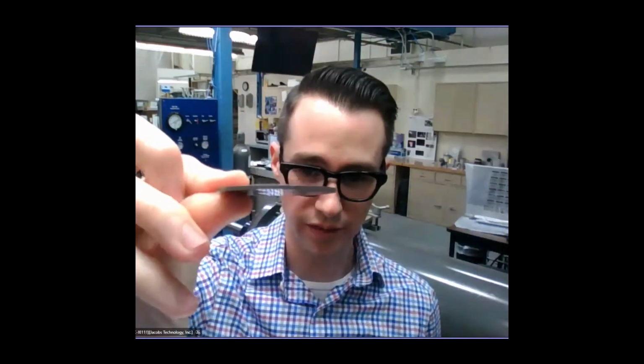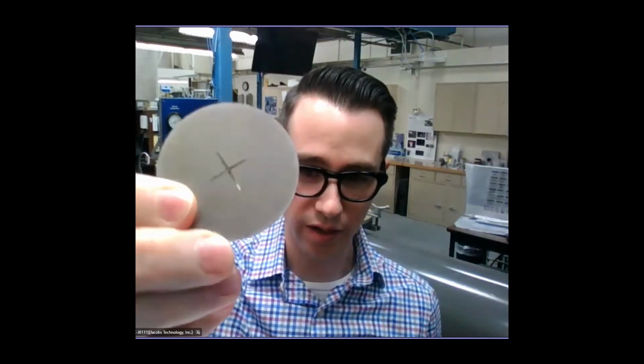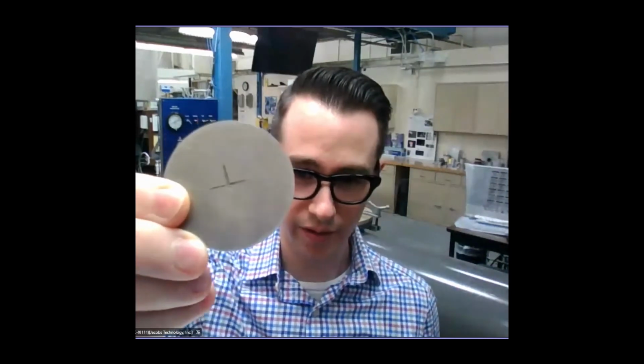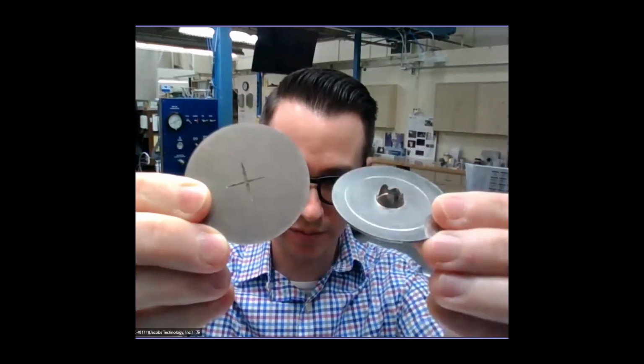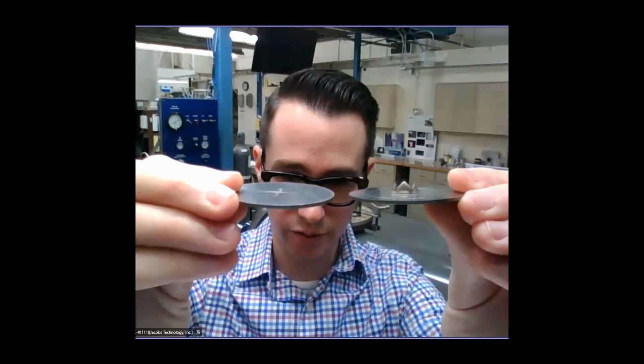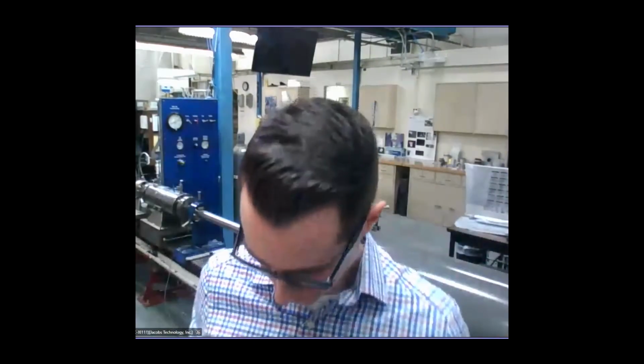As that hydrogen is getting pressurized, this is our burst disc. So it's just a thin piece of steel with a cross that's machined into it to a precision depth. And that allows it to burst at a known pressure. So this is a spent disc. And you can see when that hydrogen builds up enough pressure, it just breaks through there and then accelerates our